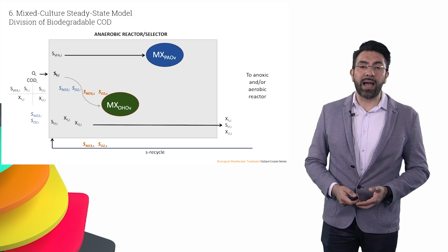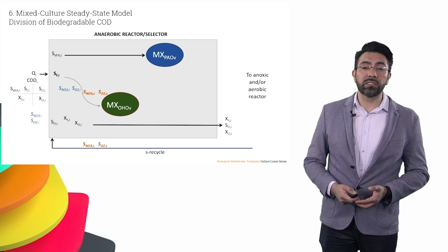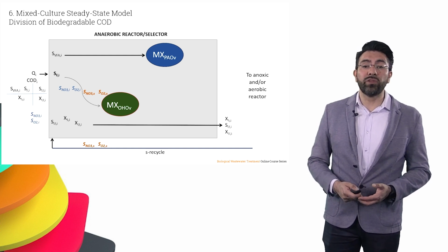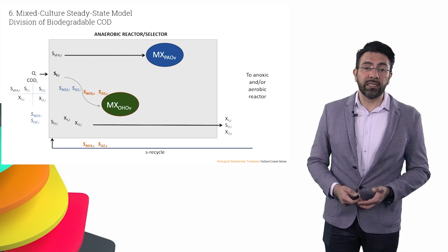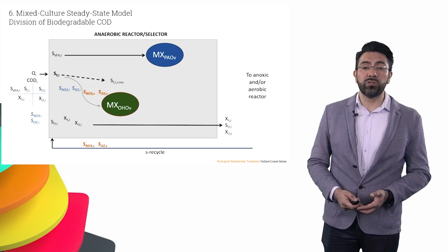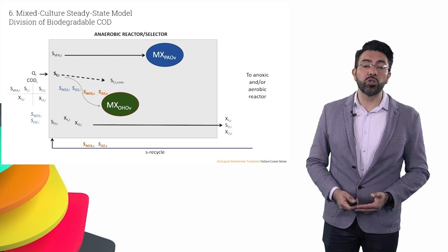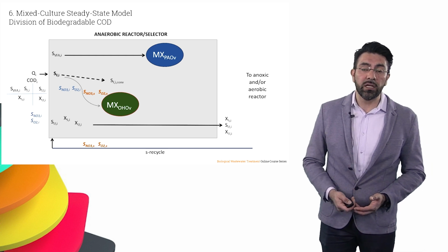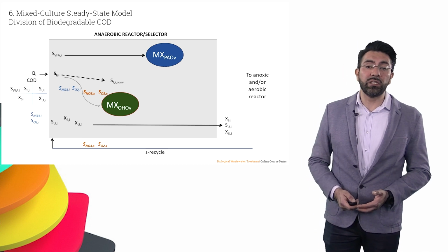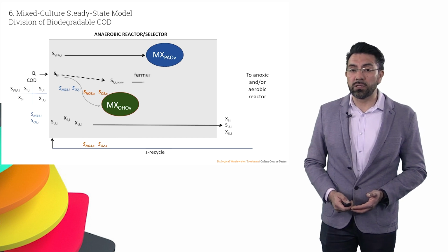This ordinary heterotrophic biomass is inactive under anaerobic conditions, but because these two electron acceptors are present, they may be able to start to consume part of the COD that is present in the inflow, in particular the fermentable COD. So from the initial fermentable COD that we have, we need to subtract the amounts that could be consumed because of the intrusion of nitrate and oxygen, so that will leave us with a certain concentration of fermentable COD that could be converted, but then we get into another restriction or another